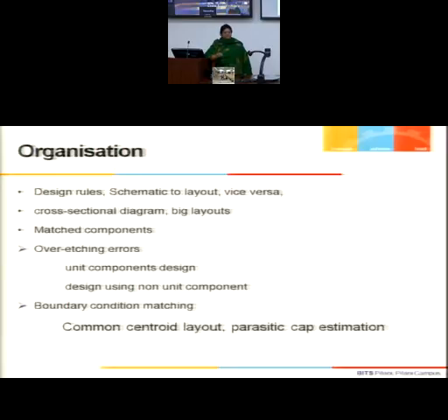Because absolute dimensions change, the current, which is dependent on the dimensional parameters W, L, tox, also changes. So in order to refine this method, in order to get good stability or reliability, I cannot say that my Q point is shifting, or that my current drive is varying, because of which the gain is changing.